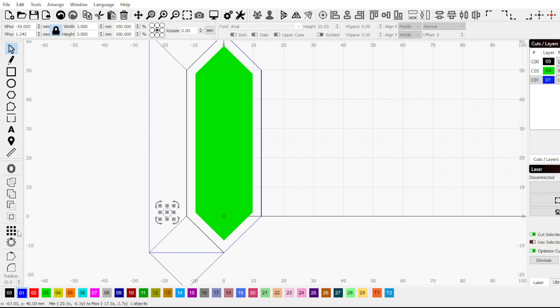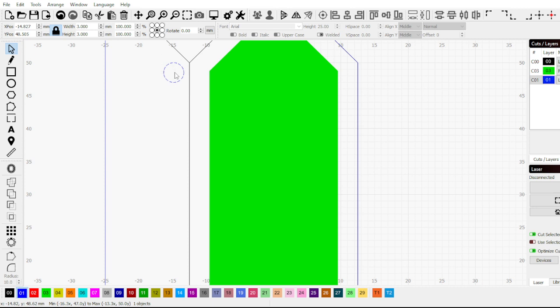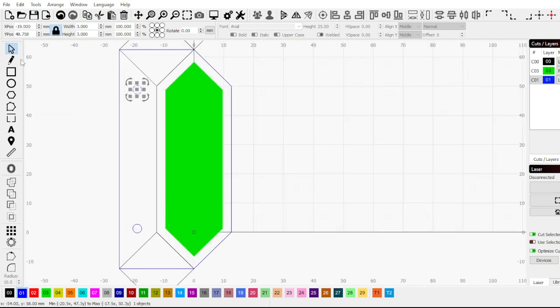And then let's do the array. And array, no, I'm just going to copy, paste it. Let's see. Copy that. Control C, Control V. Okay. Lock it onto this. And then what did I have it? -19. Which I guess would be -9.5 times 2. So -19, enter, cool. Then I'm going to draw a line from the center of this point to the center